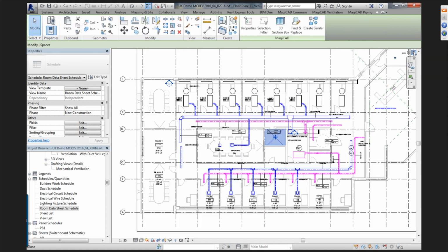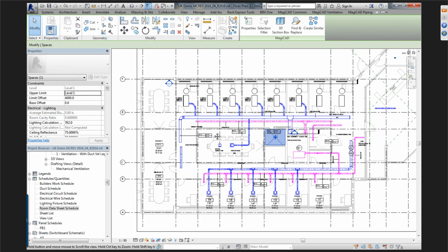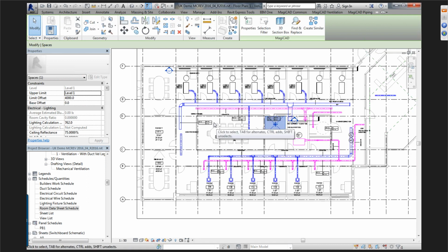And so you can then obviously populate your room data sheets with the data you want by engineers externally. So you could have technicians perhaps exporting your standard room data sheet information from Revit, the engineers populating the room data sheets themselves, and then giving it back to the technician, who then re-imports it back into the model. And then you can obviously manipulate that data with colour plans or even deliverables of schedules on drawings and things like that.